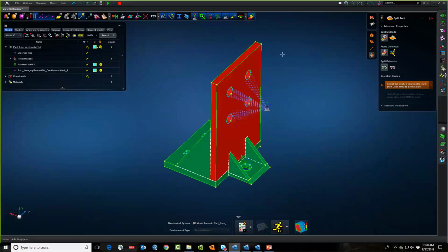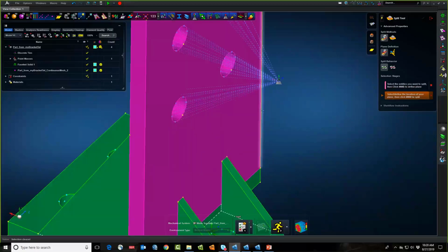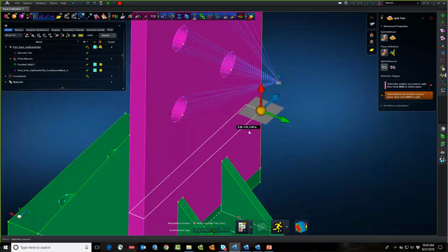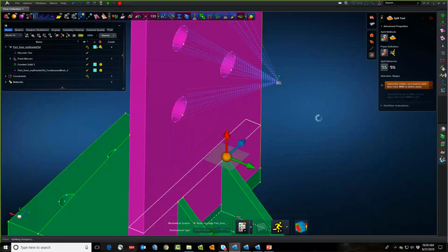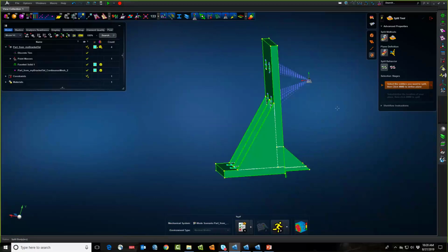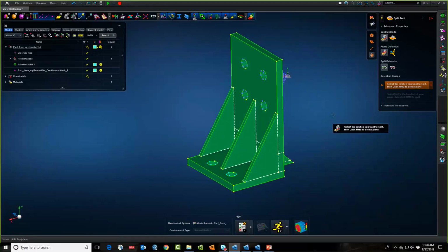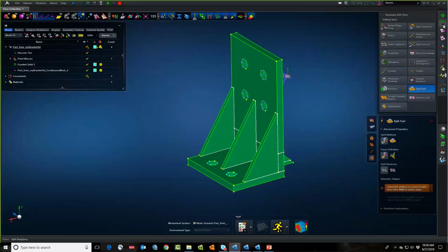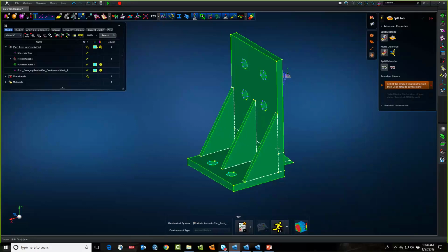Apex creates a hex mesh by sweeping things. So as soon as I get all of these areas sweepable so that the mesh will be congruent, I'll be done. I've just been splitting it at some planes until everything turns green. Now that everything is green, I know that everything here is hex meshable. I've been using the term split; maybe partition would be a better term. I've just been partitioning it. And of course, you can see the dotted white lines that represent the split between the partitions.